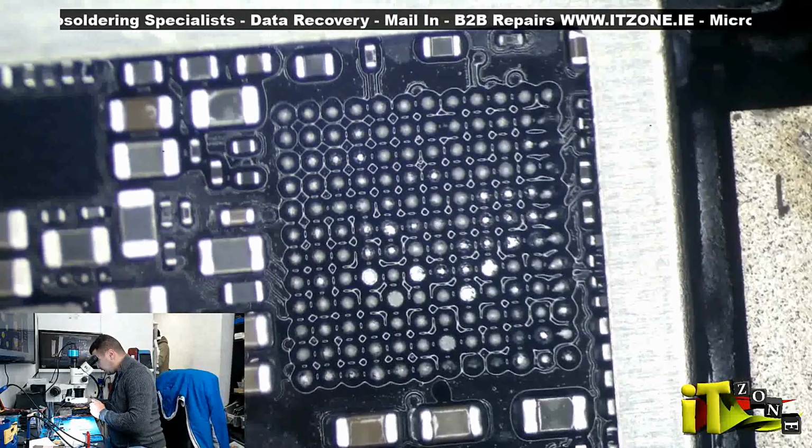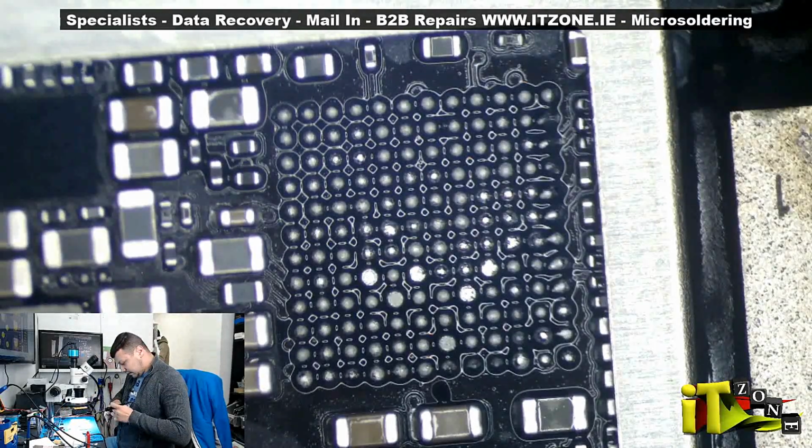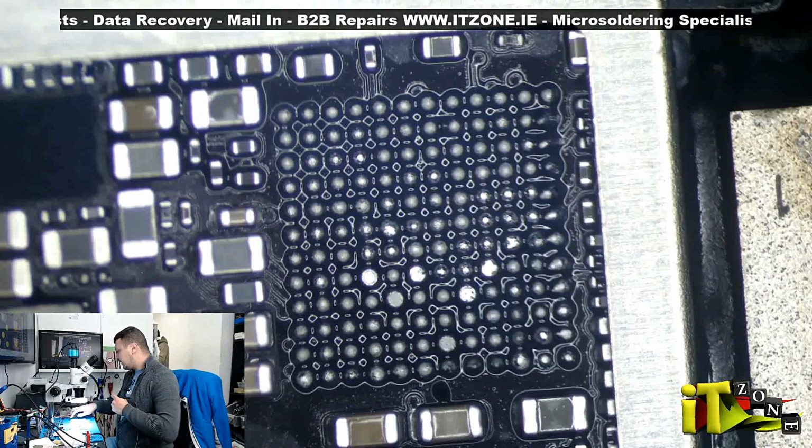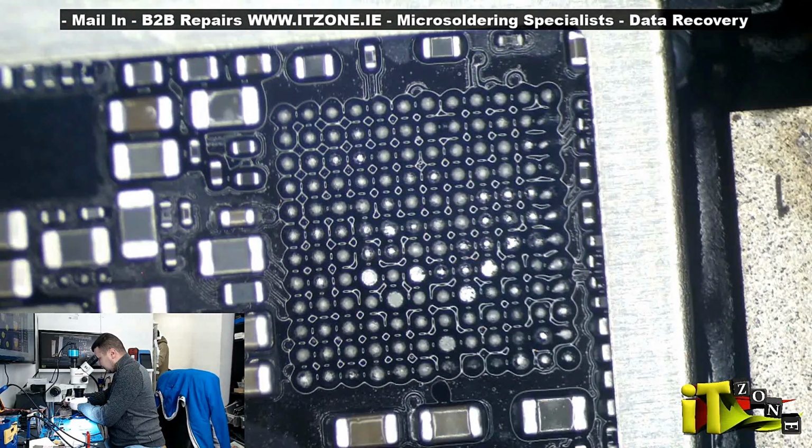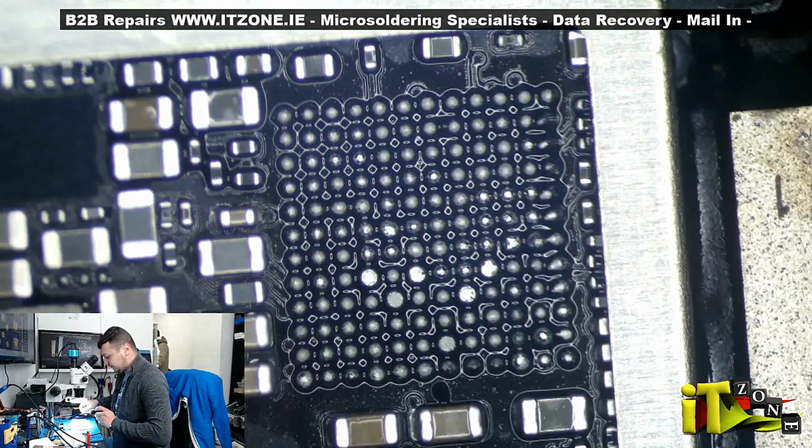Okay, so the IC is out. I'm gonna use some wick and clean the pads. Then I'm gonna run our jumper.